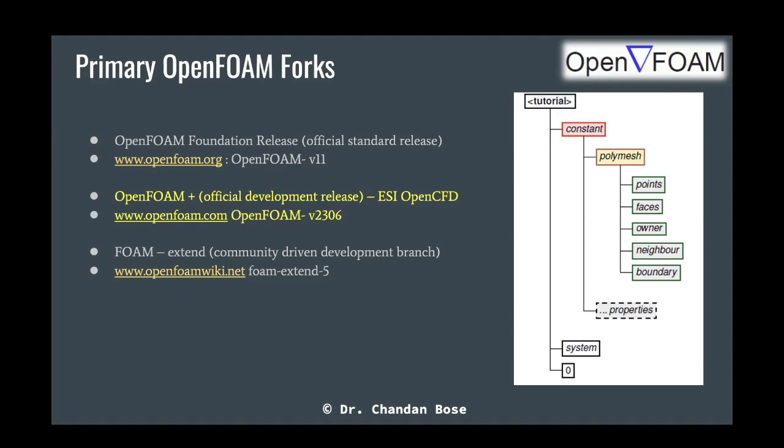How do you want to discretize the divergence term, etc.? All those schemes have a certain level of accuracy, whether first order or second order accurate in space and time. Accordingly, you choose the schemes, which will be located in fvSchemes.